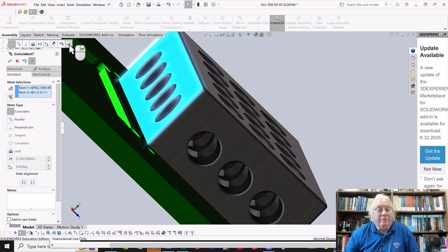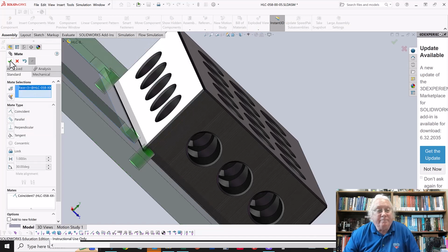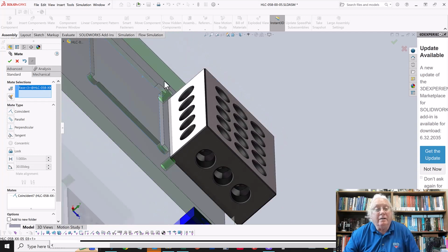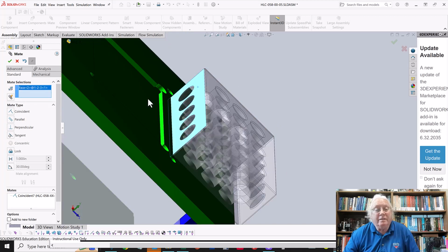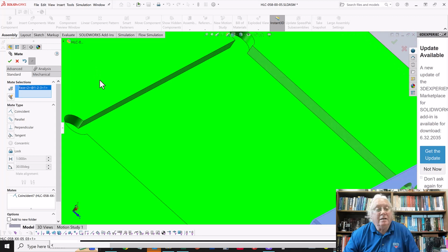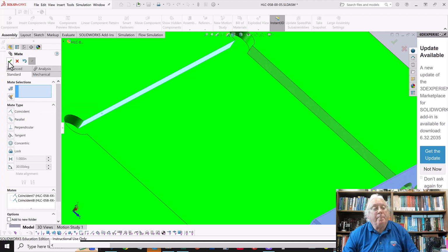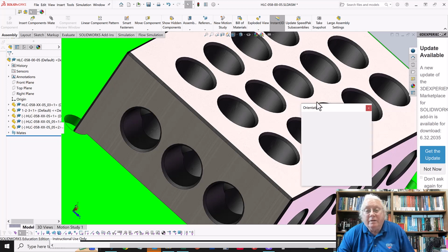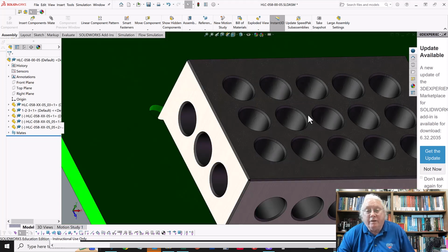And like I said, we'll be learning how to do these assembly models in assignment 6. So you have to take my word for it here. What am I doing here? Why didn't it like that? Oh, I didn't grab this face. I want that face to line up with that face. That looks better. Okay, so now the 321 block is sitting nice and snug in that pocket. So now that gauge block has all of its degrees of freedom tied down.